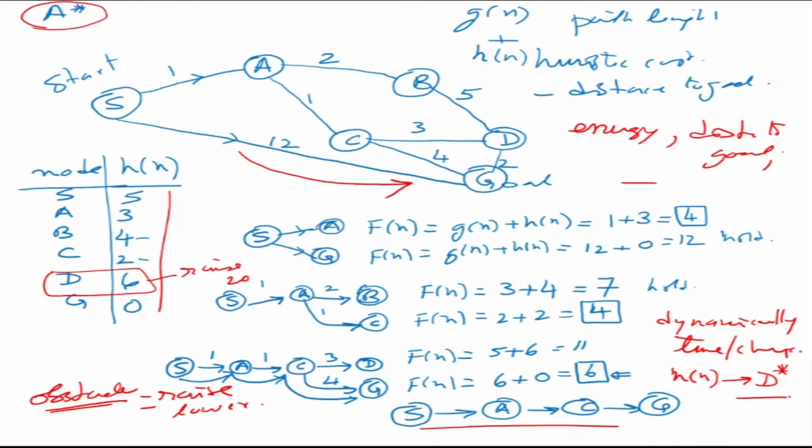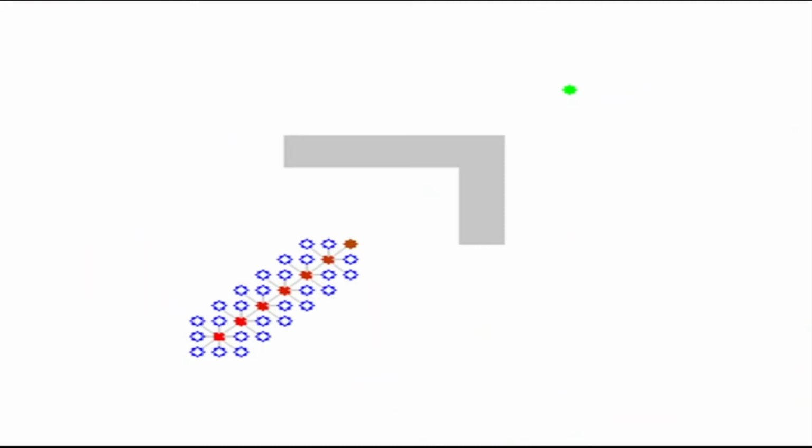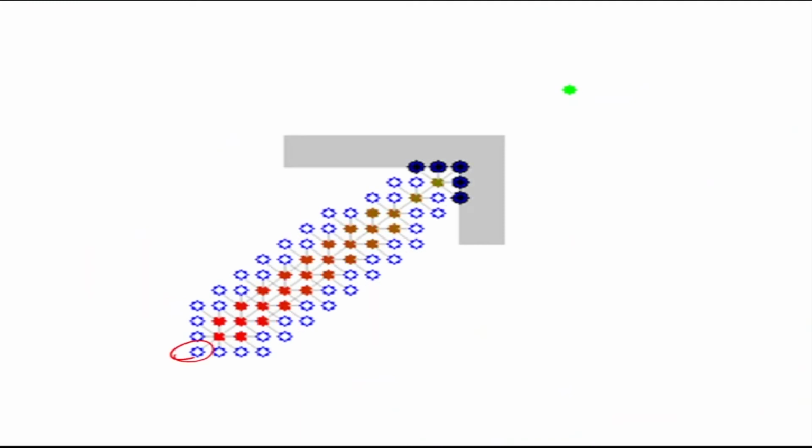So we looked at blind search, then we looked at Dijkstra's algorithm, we looked at A star. Now D star or dynamic A star is exactly the same as A star, the only difference being that you can raise or lower those weights as you go along, okay. So the robot doesn't get stuck somewhere, or if there's an obstacle, the robot understands that there's an obstacle there now. So here you can look at an example where there is a start point and a goal.